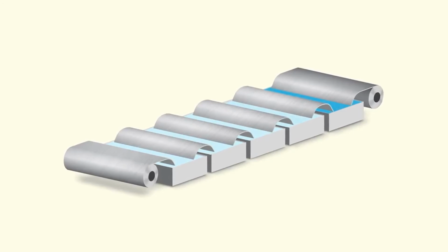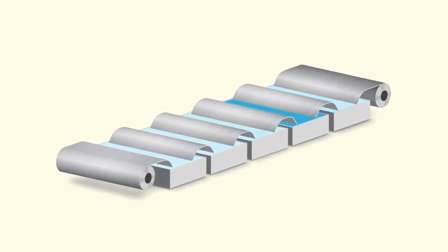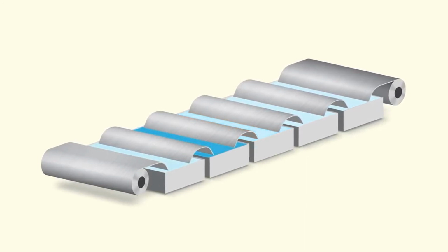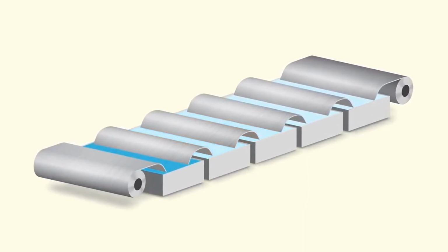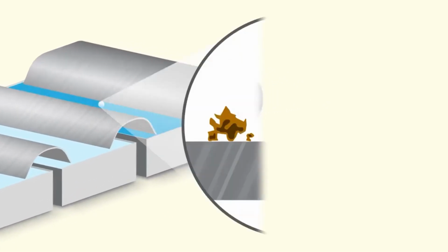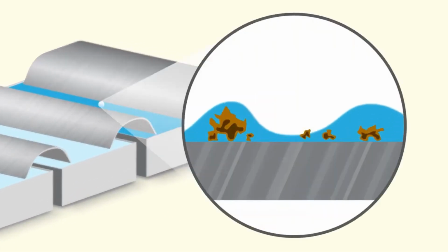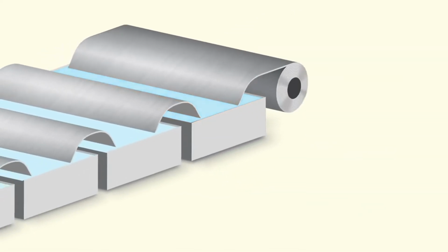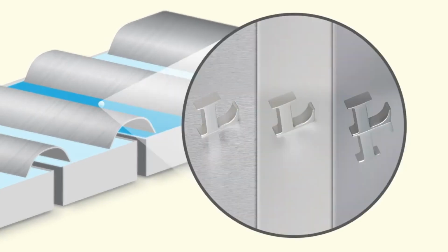The anodizing process consists of 5 steps, which offer opportunities to customize the anodic thickness, brightness, and color, ensuring that the finished aluminum meets the requirements of the end user's applications. The first step in the anodizing process is pretreatment, where the aluminum is cleaned to remove mill oils. Step 2, depending on preference, the anodizer can treat the surface for a satin, matte, or bright look.